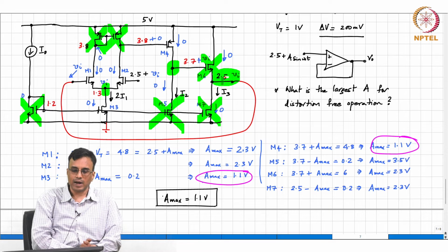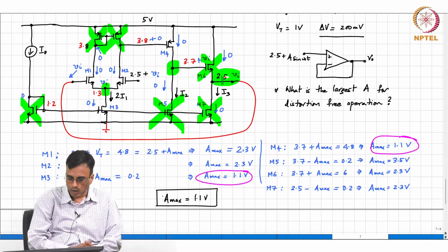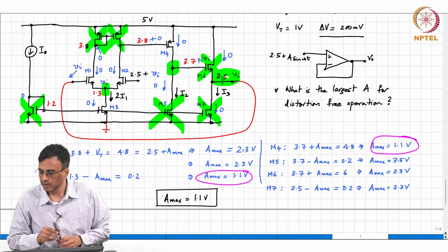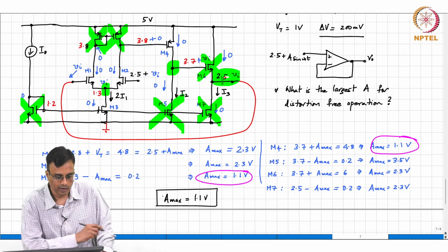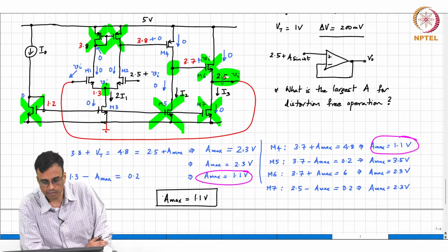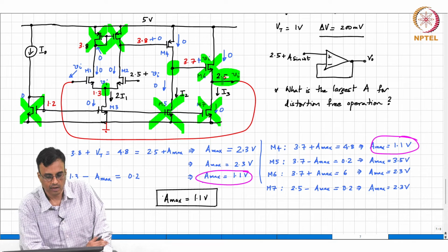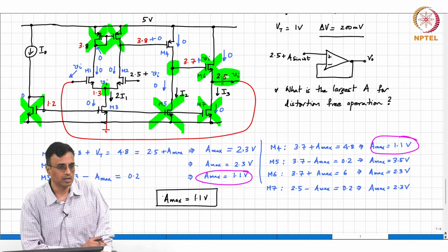In this attempt to get more and more gain, the price you pay is that you pick up more and more delay, and when you close the loop, you end up with this potential for instability. So this basically is all I had to say about the DC properties of a two-stage operational amplifier.